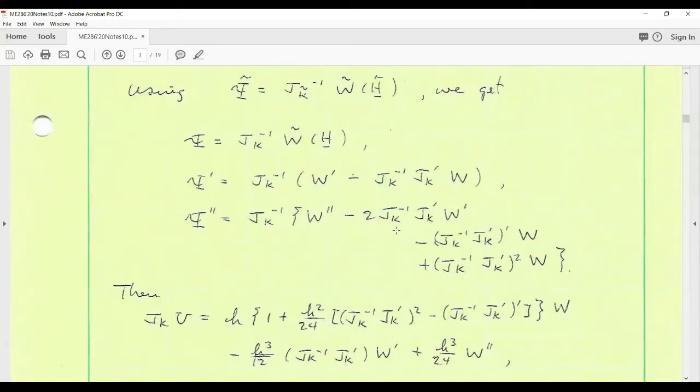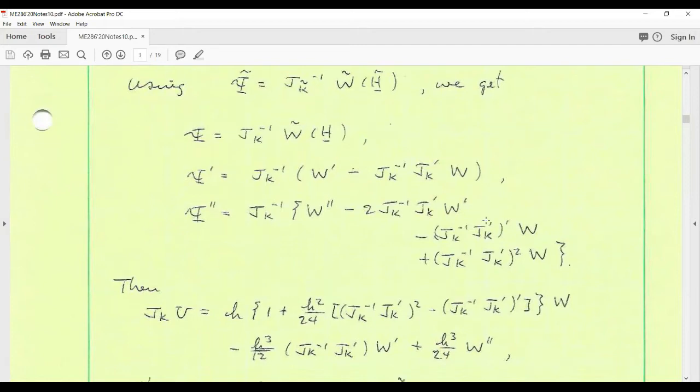If the initial plastic deformation is k equals the identity, let's say, then the typical flow rule will give you that jk never changes from the value 1 throughout the body, and therefore the through thickness derivatives would all be identically 0 throughout the body, because jk would be identically 1 throughout the body. But we can keep the general situation for now.